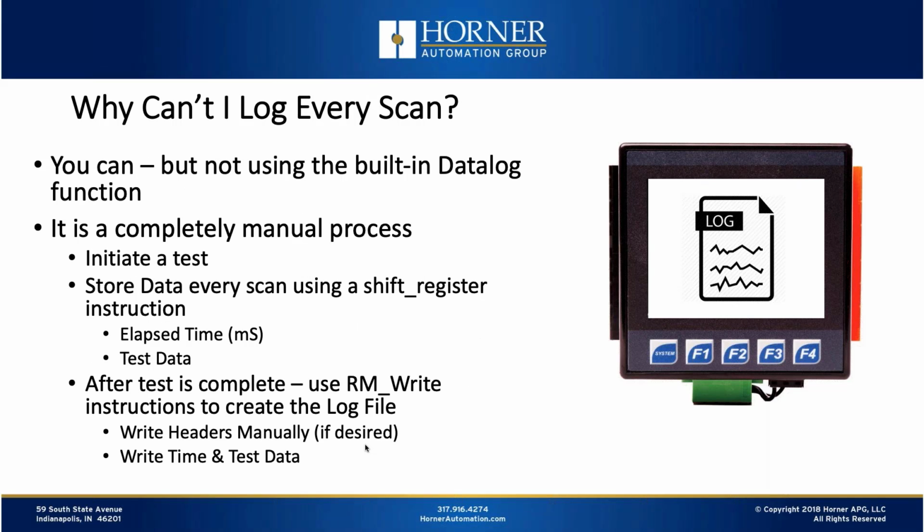Now, here's a question I've been asked before: why can't I log every scan? In our last demonstration, we were logging every other scan. The answer is yes, you can log every scan if you choose, but you can't do that using the built-in data log function.